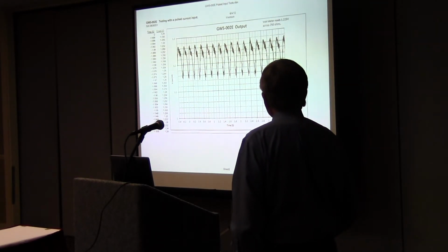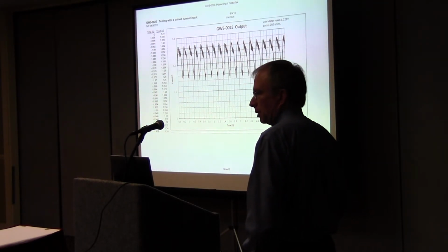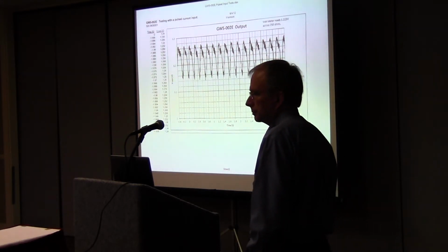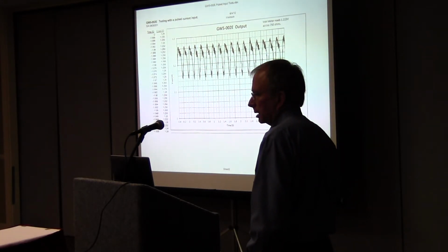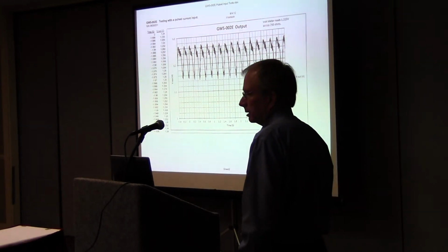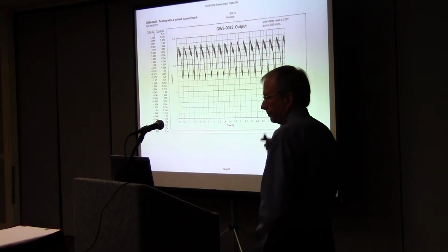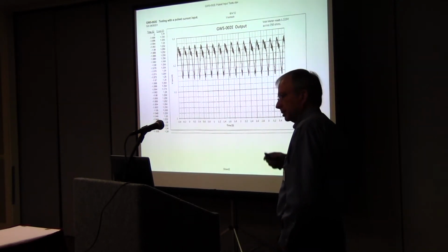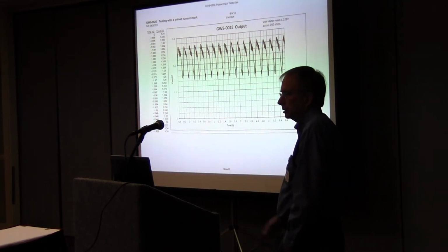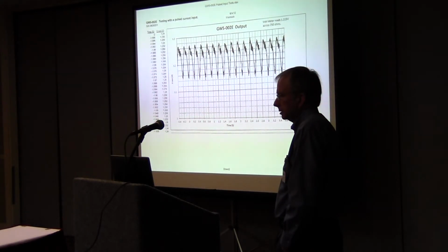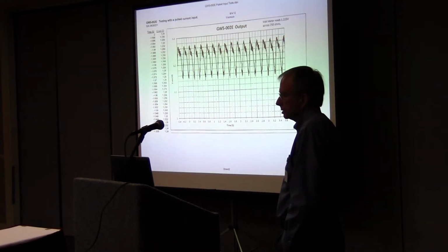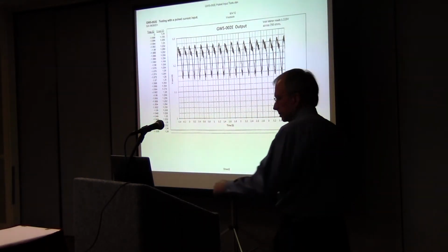The average value was correct, but when he's trying to read that with his data logging equipment, that's a big problem. So on average it was right, but it had a lot of beat frequency ripple in it, and it was because of the rate that we did the pulse height, pulse width modulation beating against the harmonics in the signal.